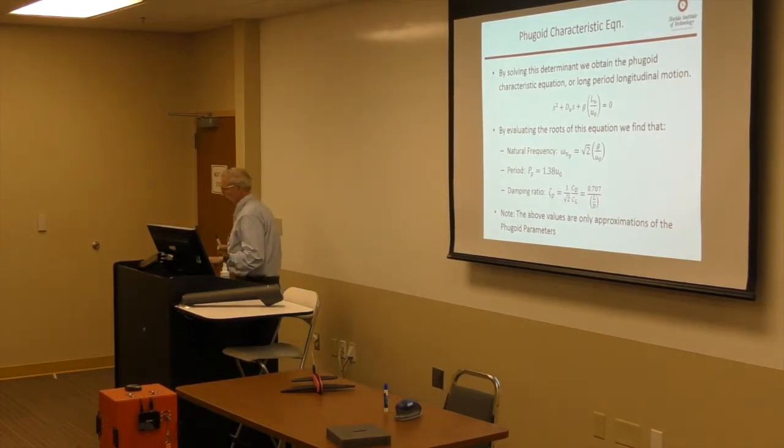So what does that tell us? What it tells us is that the lift and the drag of the airplane is going to affect the long period motion. Because what's going on as the airplane is going away from trim, nose up, okay, drag, what's happening to the drag? Drag's going down as the airspeed decreases, right? And when it starts back down, drag increases. So if you fly beside an airplane doing a phugoid, it looks like it's on a spring. Sitting out there, it goes up and down. If you match airspeeds with an airplane doing a phugoid, you watch him and he does this. You can kind of see the spring mass damper thing going on, okay, and that's why it ends up being used.